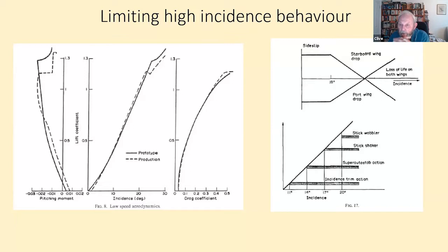But as you increase incidence on the Delta aircraft, the point at which they break down moves closer and closer to the wing. And when you get side slip on it as well, you can find that above about 18 degrees angle of attack on Concorde, the vortex breaks down on one side of the wing, and you get wing drop. Similarly on the other one, but if you get high enough to about 20, then you just get loss of lift on both of them.